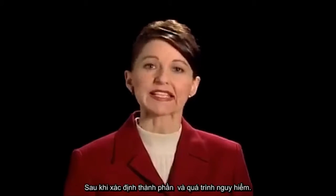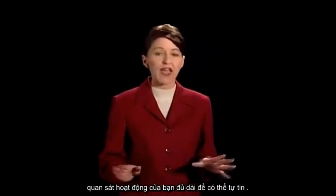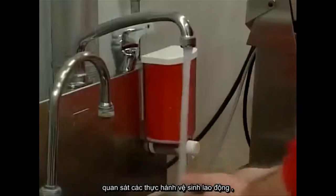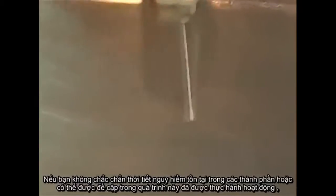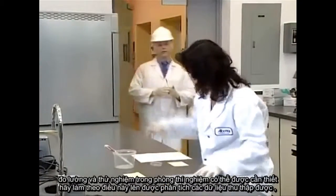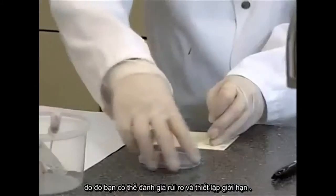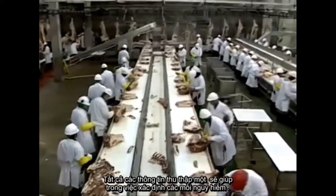After identifying ingredient and process hazards, it's time to identify hazards associated with operating practices. Observe your operations long enough to be confident they are the usual process or practice. Observe the hygienic practices of employees. Look for cross-contamination after processing. If you're uncertain whether hazards exist in the ingredients or can be introduced in the process or operating practices, measurement and laboratory testing could be needed. Be sure to follow this up by analyzing the collected data so you can assess risks and set limits. All the information collected so far will help you in identifying hazards.